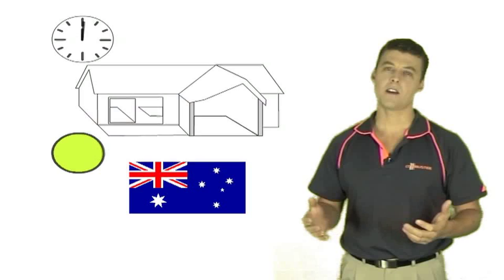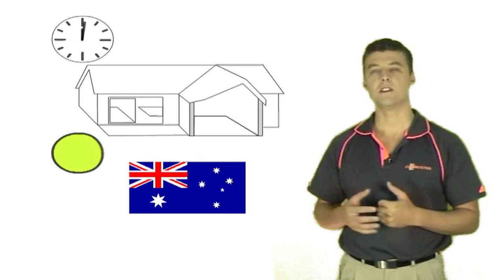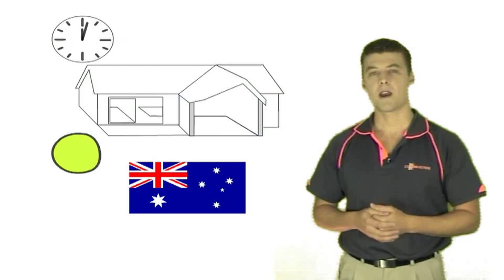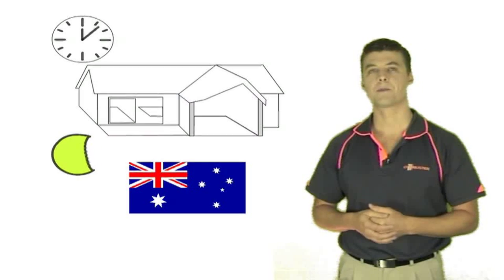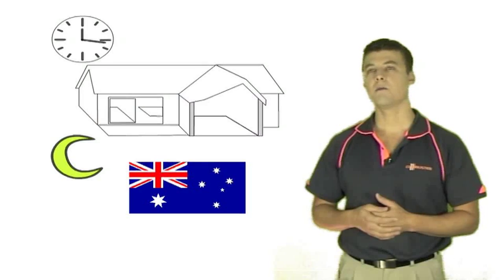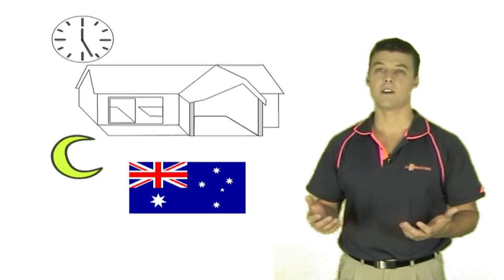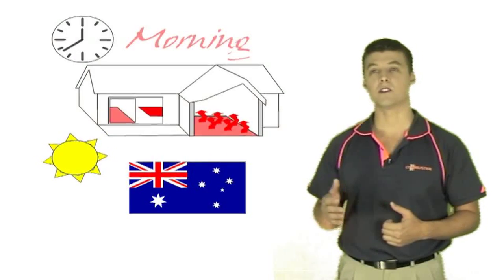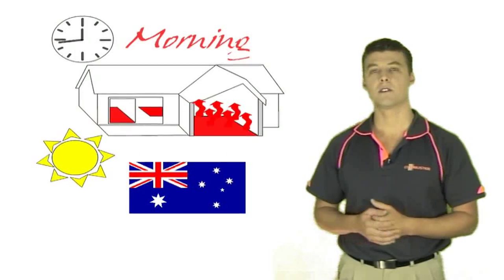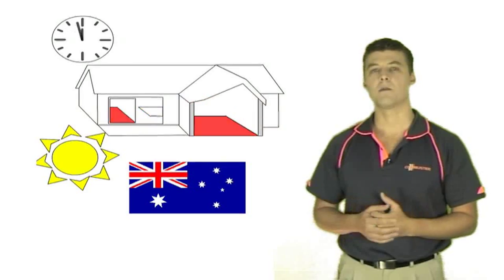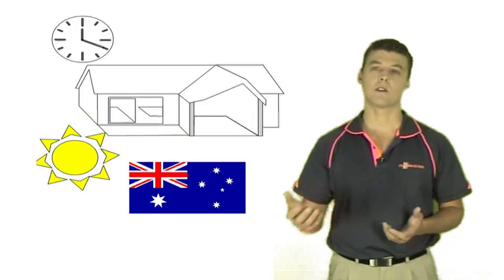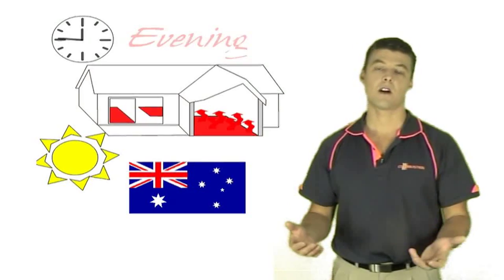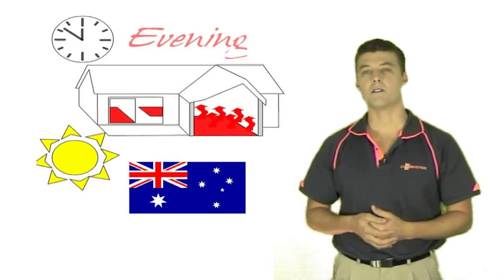Firstly, Australian architecture doesn't generally have the insulation values required to store heat efficiently and make slab heating economical. Secondly, Australian winter weather varies daily and even hourly, so an on-demand system works more efficiently in heating short, discrete periods. With an on-demand system, each room can be heated according to its own pre-programmed times during the cold mornings and cold evenings when it is required.